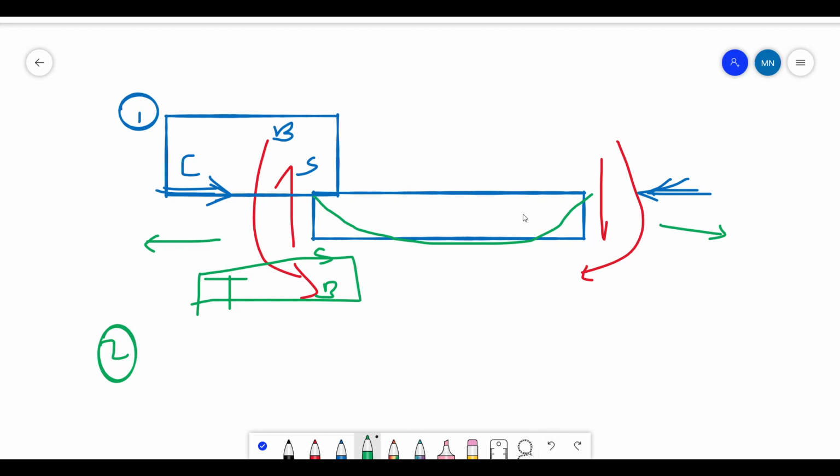So for the beam, we may need a higher section. But in the similar case, when the beam is subject to tension and then shear and bending, it tries to pull this side as well as this side. So it reduces your section requirement, and steel is good in tension, so you can reduce the weight of the structure if the members are subjected to tension rather than compression.